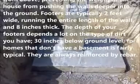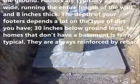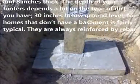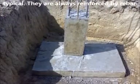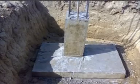The depth of your footers depends a lot on the type of dirt you have. 30 inches below ground level, for homes that don't have a basement, is fairly typical. They are always reinforced by rebar.